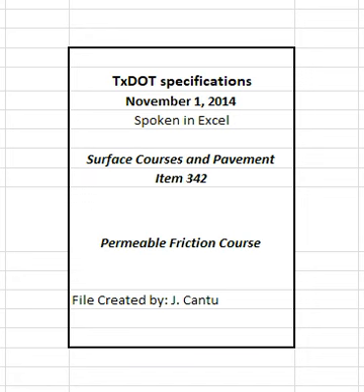2.1.1.1 Blending Class A and Class B aggregates. Class B aggregate meeting all other requirements in the table may first be blended with a Class A aggregate to meet requirements for Class A materials. However, Class B virgin, non-recycled, aggregate may be disallowed when shown on the plans. Ensure that at least 50% by weight, or volume if required, of the material retained on the number 4 sieve comes from the Class A aggregate source when blending Class A and B aggregates to meet a Class A requirement. Blend by volume if the bulk specific gravities of the Class A and B aggregates differ by more than 0.300.